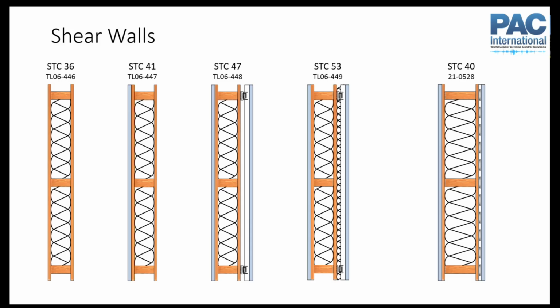And we've created this little trapped airspace, where the air acts as a spring. And so it'll transmit the vibration, the sound energy from the drywall to the plywood and then through the rest of the structure. We get this buildup of sound in this constrained space. If we put insulation in that cavity, you see we get a 6-point STC improvement, and now we get a wall that performs above code. So we've got this acoustic decoupling, but we've also taken care of this cavity path by putting the insulation in there.